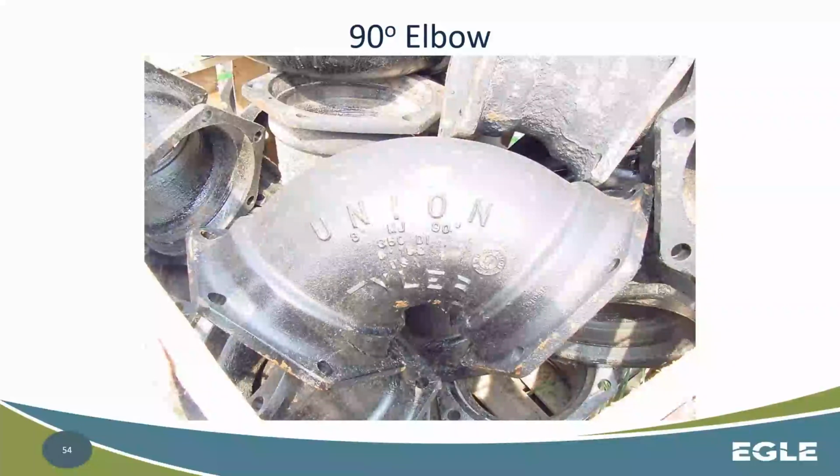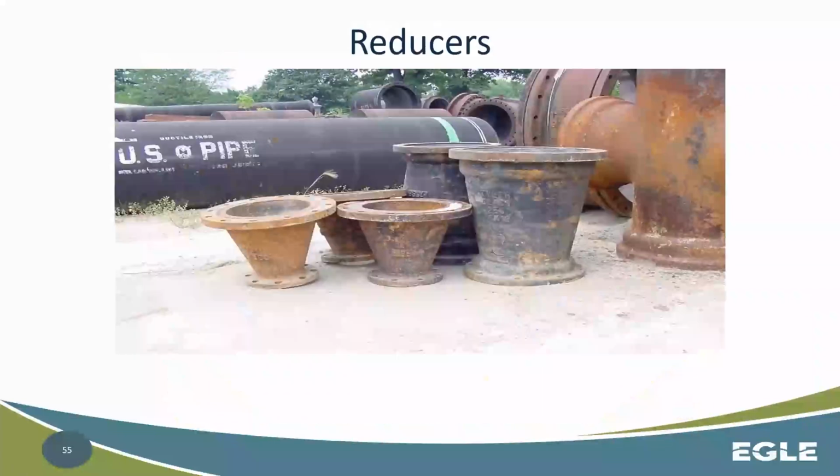Well, that would actually be a mechanical joint. And one way to tell here is that you actually have this bell end. So you'd have that bell and spigot. Yes, there are holes there that you would put that bolt through. But if you recall, that flange portion would be pushing together a gasket in between those portions. So it'd be kind of in here, rather than having that bell end going into that, and then having that mechanical joint actually pushing into the gasket at this side. Okay. So this would actually be a mechanical joint, just to get you familiar, right?